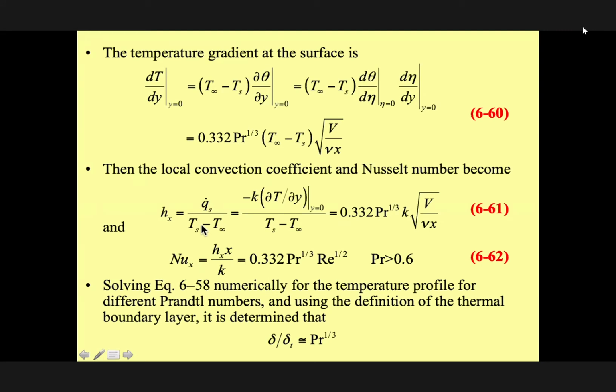The heat transfer at the boundary layer is, we can assume, by conduction through the fluid, okay? Therefore, if I am able to define the temperature profile, I can easily calculate this value. Once we calculate the temperature profile here, we have an expression, and that was the definition of the heat transfer coefficient. We put them together again and end up with a non-dimensional term. This non-dimensional term is the ratio of heat transfer by convection to conduction.